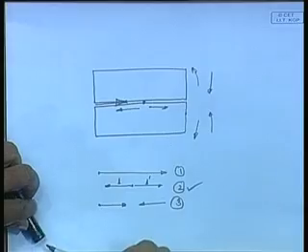In all the previous methods we have implemented some external agencies through which the effect was mitigated, the heat flow pattern was changed, some tensioning has been applied, but here the same welding is being done, but I am changing my sequence of welding, such that the effect produced by one particular weld is nullified by the other. So, that is what is sequencing of welding.